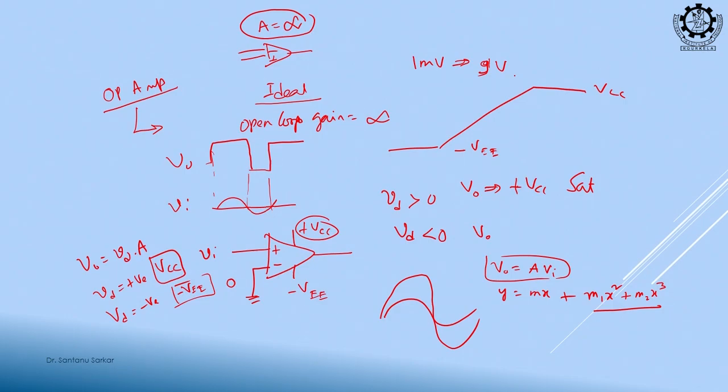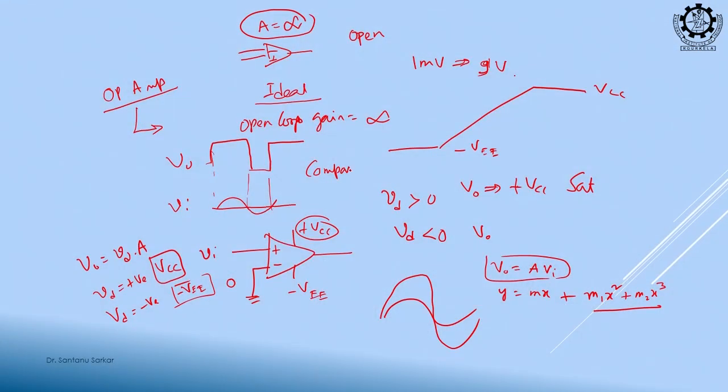So, I gave you an open loop, please understand this, this is important. You will understand a basic question, why we use feedback in an op amp. I have designed an open loop amplifier, but in open loop can I make it an amplifier? No, it becomes a comparator. In open loop it compares, right, with what does it compare?